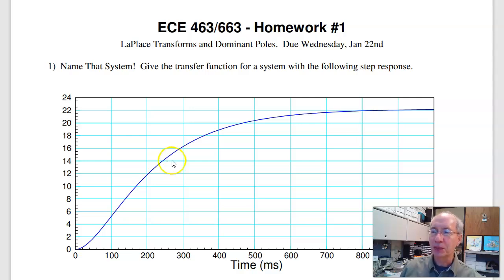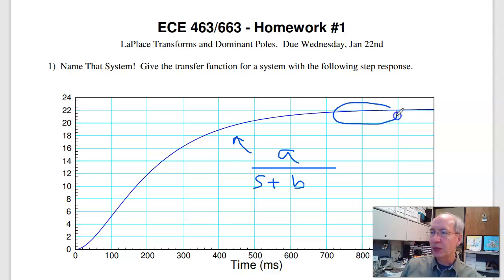This is going backwards. On the first problem, I can see that there's no oscillations, just a nice simple exponential rise that tells me right away this has a real pole. So that's roughly what the transfer function looks like. For this, I need to come up with two parameters from this graph to find my two unknowns. One of them is the 2% settling time. It's right around here. What it is exactly is kind of hard to say. If I say maybe 0.7, then B is 4 over 0.7.